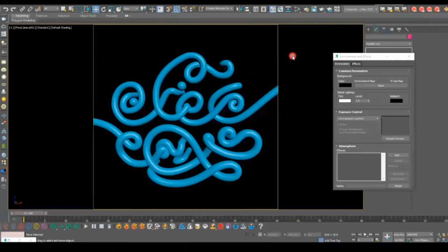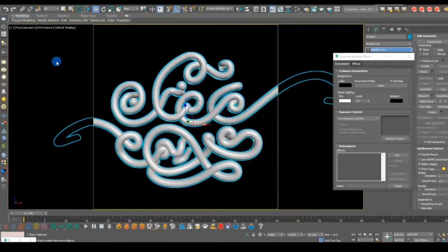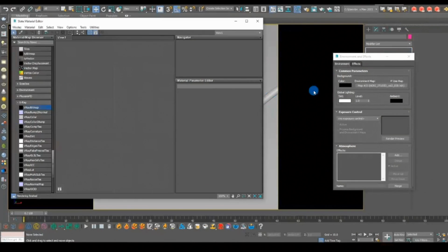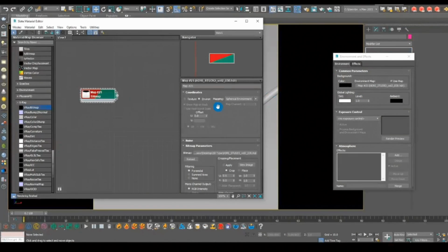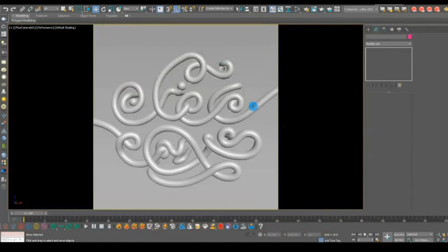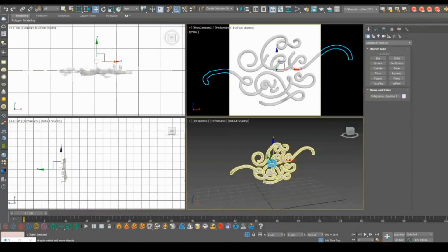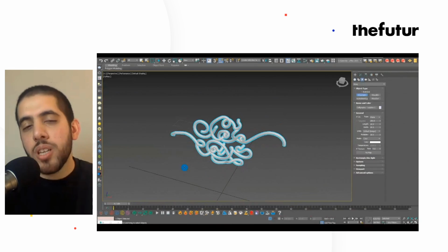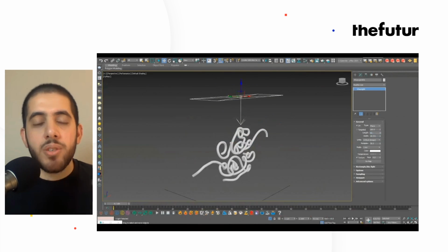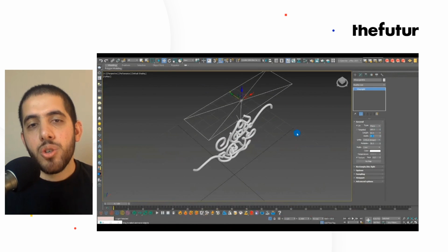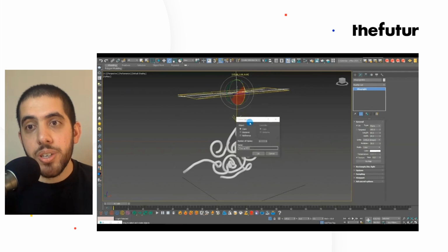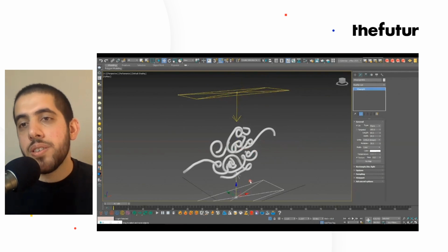And again, lighting is one of the most important topics in 3D because if you don't have good lighting, you're not going to get good shadows, good highlights. And what I like to use, instead of complicating stuff, and a lot of people use this, is something called HDRI maps. An HDRI map is almost like a panoramic image. It can be the outdoors, it can be a studio setup, and it has all your lights set up in that one image. So you place it in your scene, and it surrounds it 360 degrees, and then it just lights up your scene very nicely.